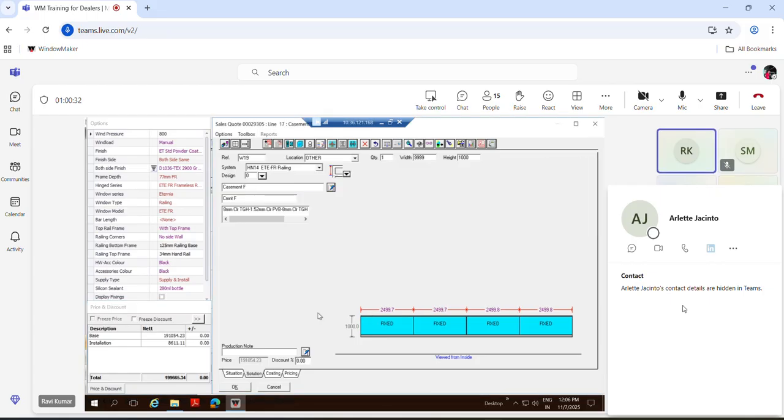So like if there is some kind of L railing or continuous railing, you can select both side wall, one side wall, or no wall. For that, you can select from the railing corner options. So you can select no side wall, one side wall, or both side wall.